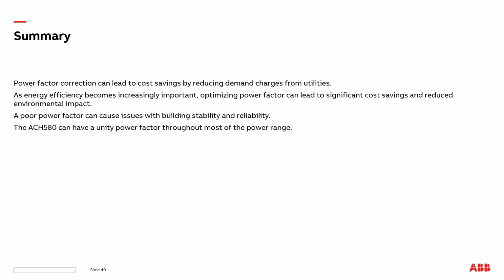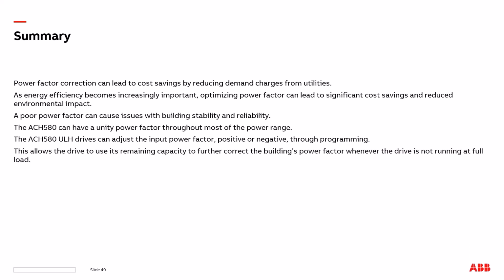The ACH580 ULH drive can have unity power factor through most of its power range, and the ACH580 ULH drive can adjust the input power factor to positive or negative through programming. This allows the drive to use its remaining capacity to further correct the building's power factor whenever the drive is not running at full load.